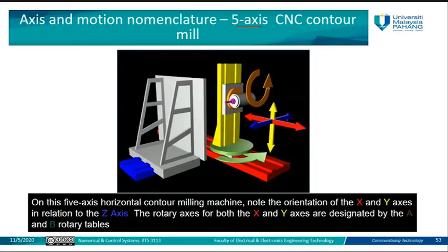As you can see the colors here, the orange, the light brown, and also the light green represent the rotary axes, or the rotary table. So this, for example, is the head, the part which is rotating here, and here we have another part which is rotating. These represent the extra 2 axes in addition to the original 3 axes. X is the red one, which moves this way and that way, and Z moves that way. This part will be moving towards or away from the workpiece, and Y is represented by the vertical movement up or down, in addition to the rotating bar.